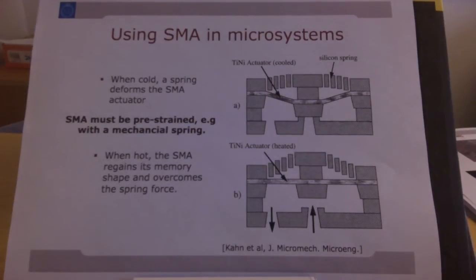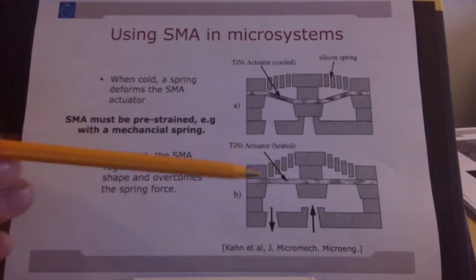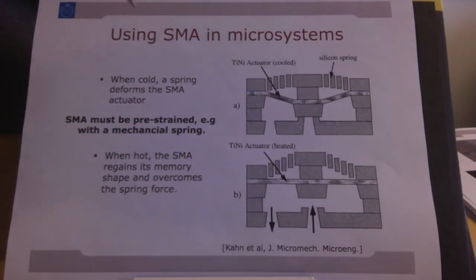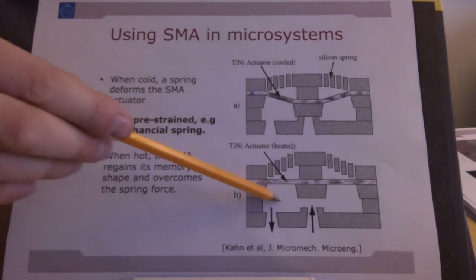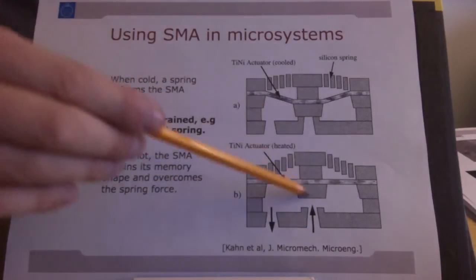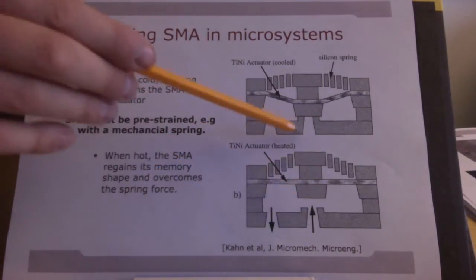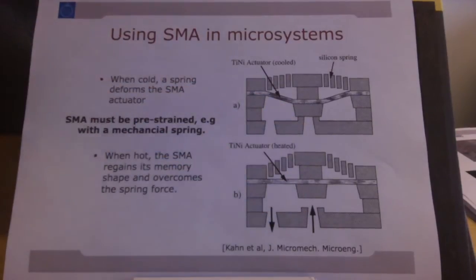And here we see an example of how that is done. We see it by an example of a microvalve. Basically a microvalve is a structure, in this case a gas microvalve, that controls the airflow. The air comes into the bottom orifice and goes out of the top orifice, and in the open state of course the air can flow, and in the closed state this boss structure is pressed down, and then there's no flow possible. So this is an open-closed microvalve system.